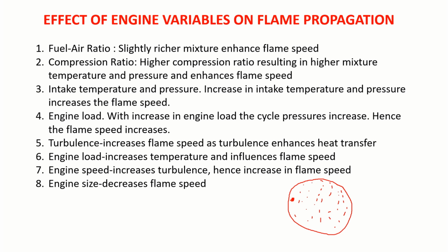Now I pass the spark. After the ignition lag, a small flame front will appear. Then this grows like this and starts traveling with a certain speed.